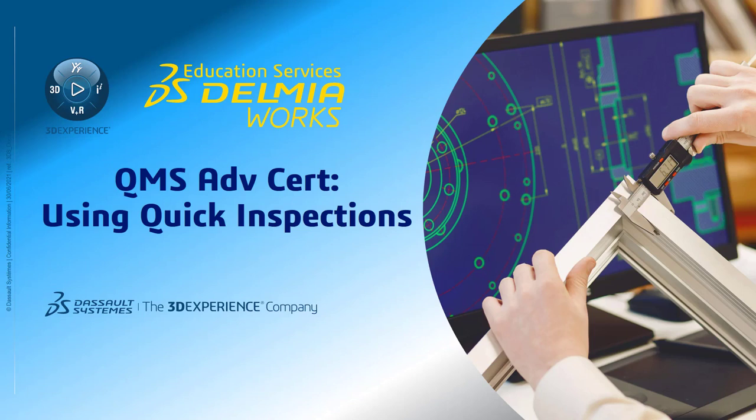Today we're going to talk about that function in DELMIAWorks where you set up and use quick inspections. Inspection setups and quick inspections work together to allow users to consistently check the quality of items during the manufacturing process. These details are created in the inspection setup module, and once those inspections are established, the user only needs to enter the data in the desired parameters to be measured, and then that data is automatically transferred to our statistical process control analysis database.